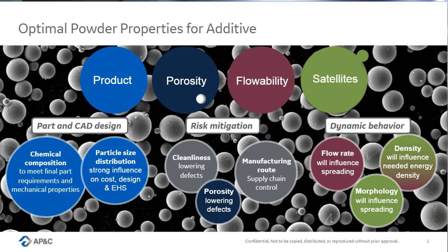but also the interstitials, the amount of oxygen, nitrogen, hydrogen, carbon, because even more when we're talking about titanium and in the medical industry, oxygen will drive the mechanical properties. So it's important to monitor that and define that properly. And particle size distribution, we already discussed pretty much about that, so I won't go into details. There's everything that I consider the dynamic behavior of the powder, so how it's going to be easy to spread on your powder bed, how you're going to be able to see it, how you're going to convey it.